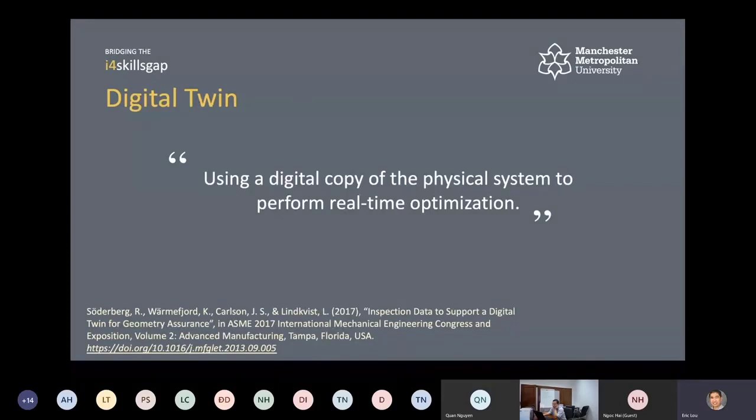So why are we doing all this? We ask the question: why do we want to do Scan-to-BIM? Why do we want to recreate our analog world? What we want is to have a digital twin. In the UK, we have a lot of existing buildings that we cannot demolish, so we need to refurbish. To refurbish the building in a more efficient manner, we need a digital twin, because we need to model energy, daylight, and a lot of things within the building. With an accurate digital twin, we are now able to perform any refurbishment or retrofit